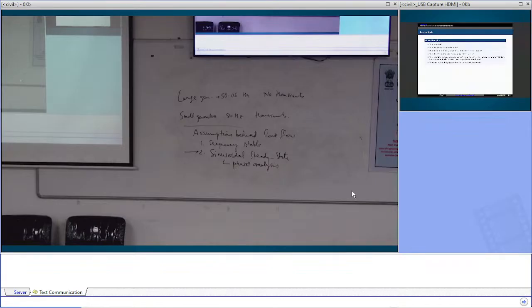We assume that this network, and we just said that there is load and generation imbalance, right? And then we change the frequency. And voltage levels are changing all the time. So when do we get transients? If I have an RC circuit, when do we get transients? If I change the voltage, will I get transients? I have an RC circuit, I am applying 10 volts, suddenly I change it to 15 volts. Will you get transients? If I have an RC circuit and I changed its voltage from 10 to 15, will transients come? They will come, right? And we are changing voltages every instant. The synchronous machine's voltage changes or not? And now you are also saying we change the frequency also. So then how is this assumption valid?